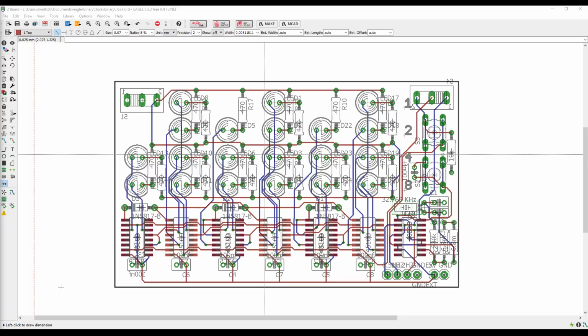And I realized I could do it with 7-segment displays using a combination of the 4510, my 1 Hertz timer that I knocked up previously for the frequency counter project, still not finished, and then 4511s to drive 7-segment displays, which I covered in that 4000 series, which sort of hasn't stopped.